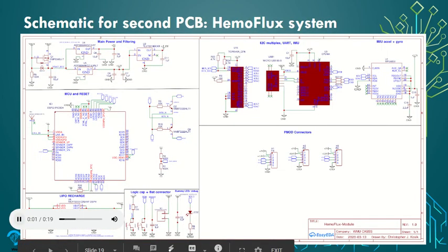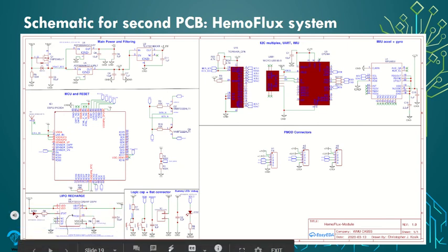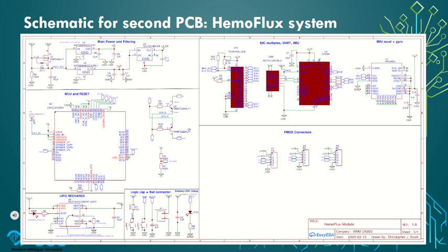The second version of the system schematic is shown. Specifically, this is the schematic of the main microcontroller board. As you can see, the PPG sensors are replaced by the dual-point wire connections. There are other minor changes, including new resistors, capacitors, and new pin connections to the ESP32.